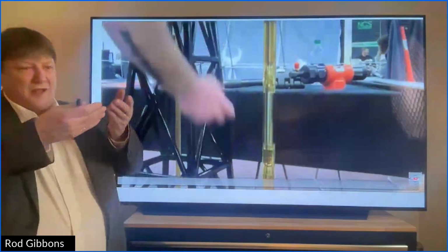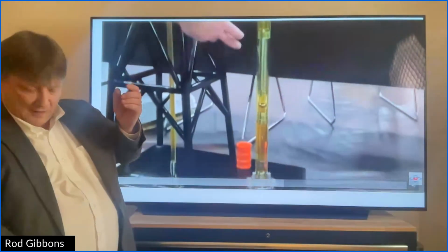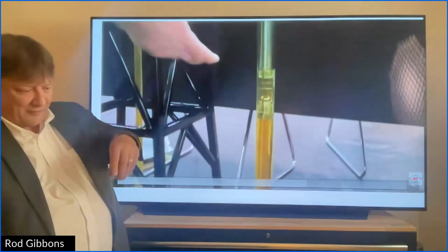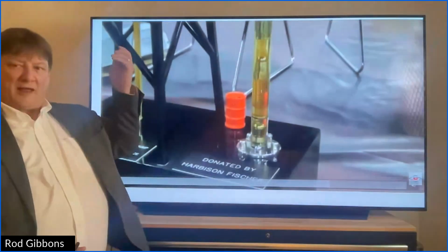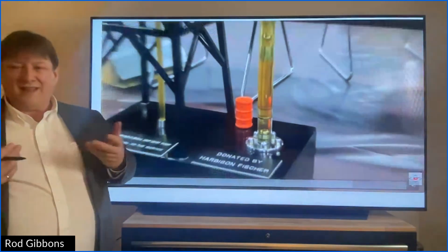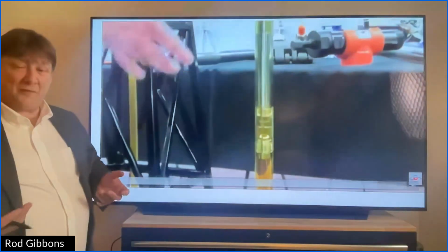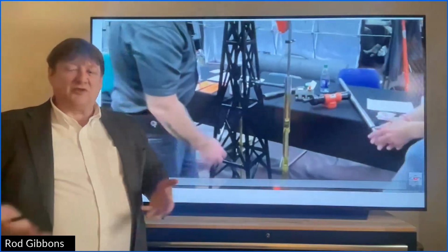Then when it goes on its downstroke, now the standing valve is in position. It sits on its seat and the traveling valve floats down and then picks that fluid back up. Stroke by stroke, that's what pumps the oil out of the well. And you're doing this because there's not enough energy in the reservoir to drive the oil out.